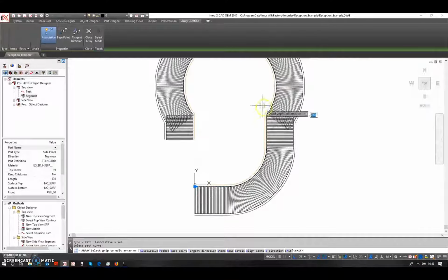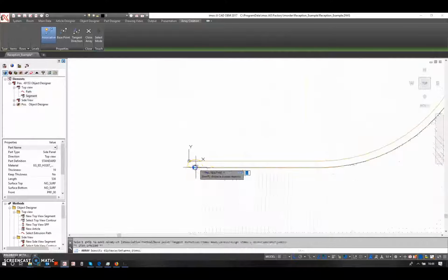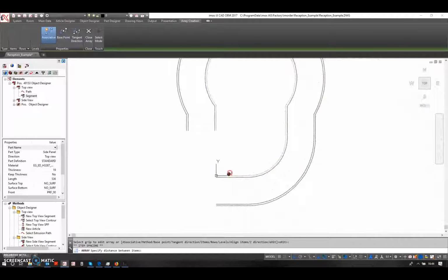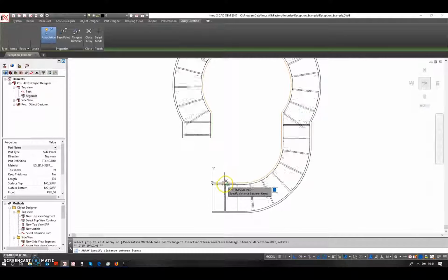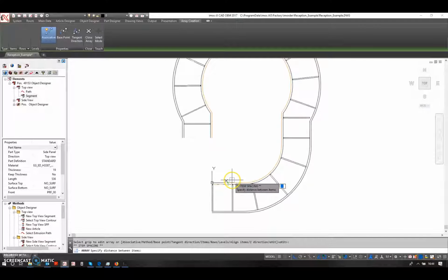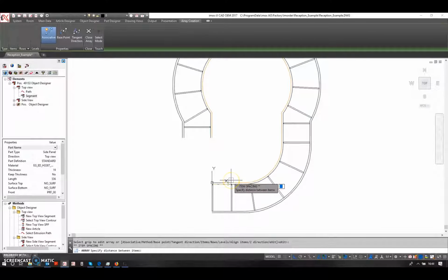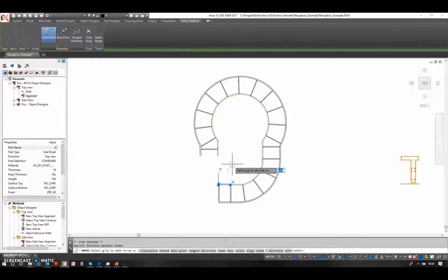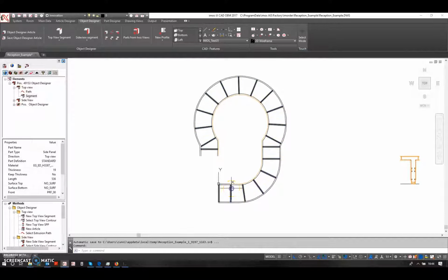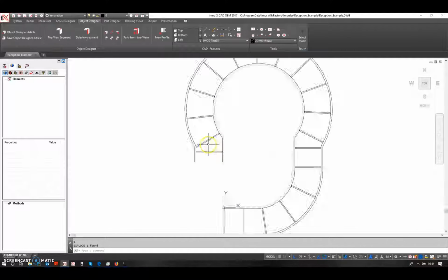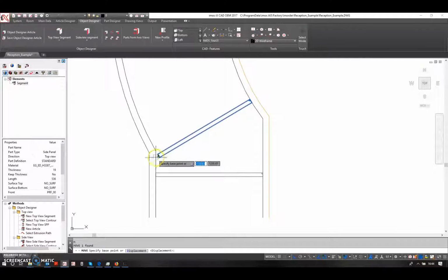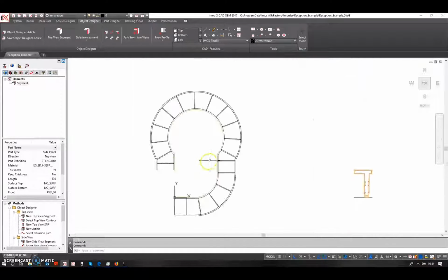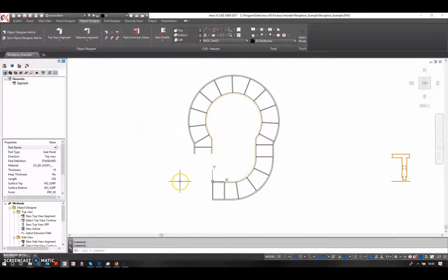Now this is far too many uprights, that's okay. I can just space this out, and I'm just going to eyeball it at this point and choose what I need to make this look quite nice. So I'm going to say somewhere around here looks okay, and then I'm going to explode this setting, and I can then move these around. So I might want to bring this one back here a little bit more, and I can add in more, and I can take them out depending on where I want them to be set for splits.